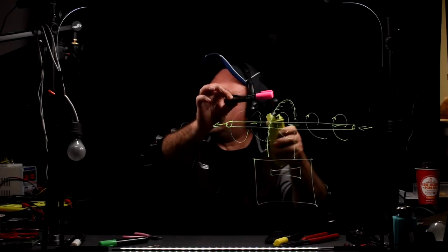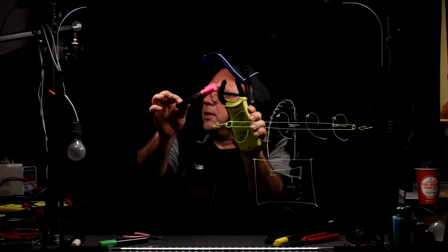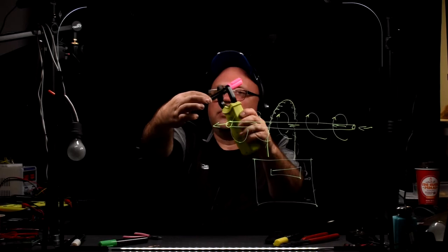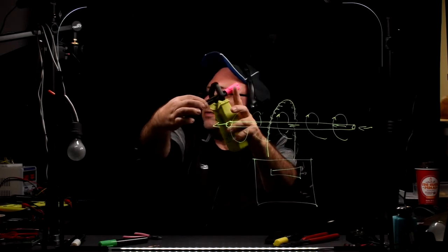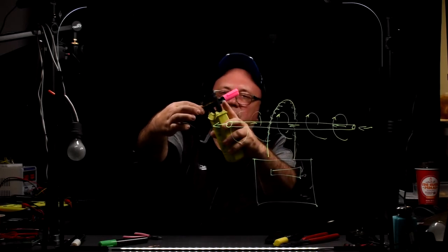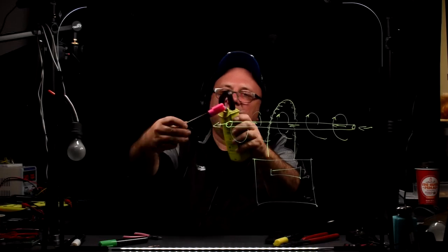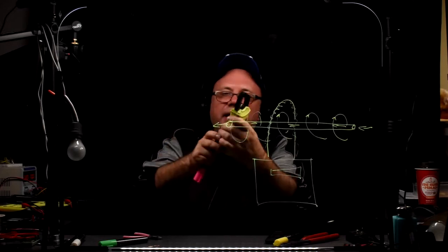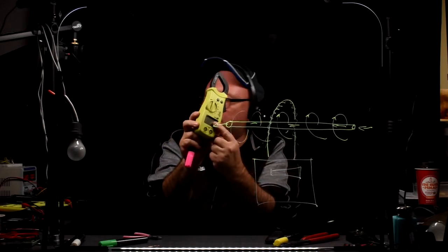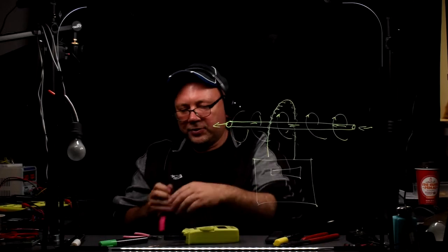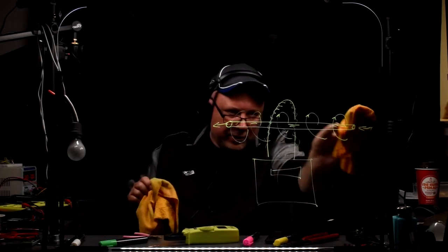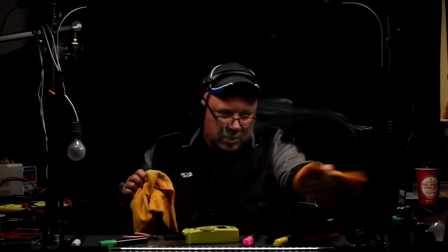So how do we do that? Let's say this is a wire. We open the clamp and put it around the wire. If the current flows through this wire, it would cause an electromagnetic field. This element would sense that, and the value of the current would be displayed here. So that's all about the theory, sort of surface-scratching theory on the clamp-on meters.